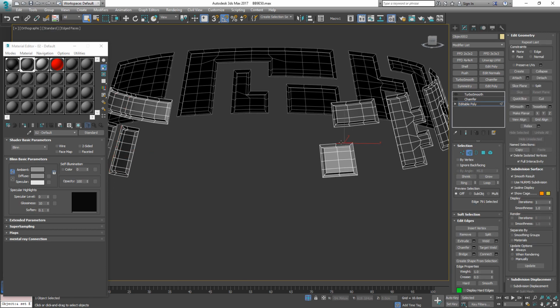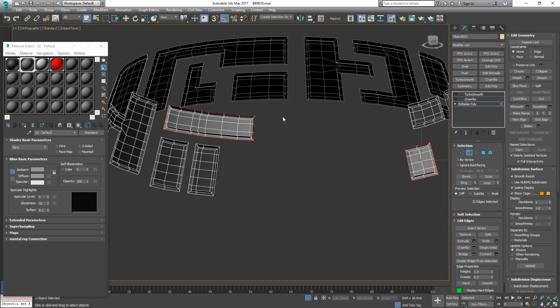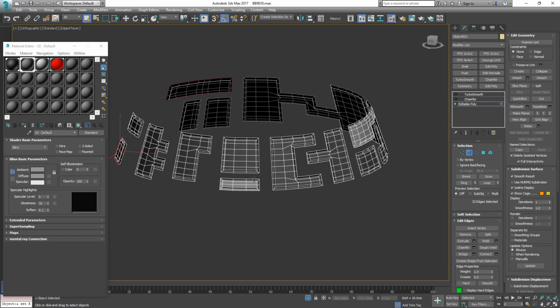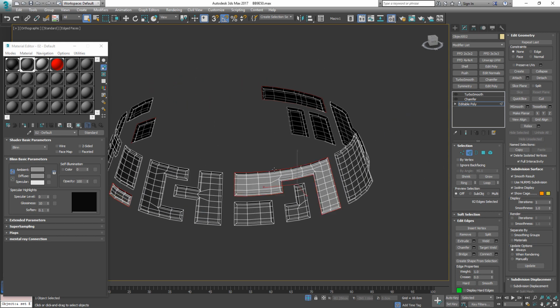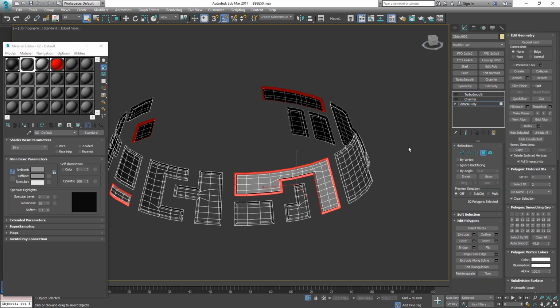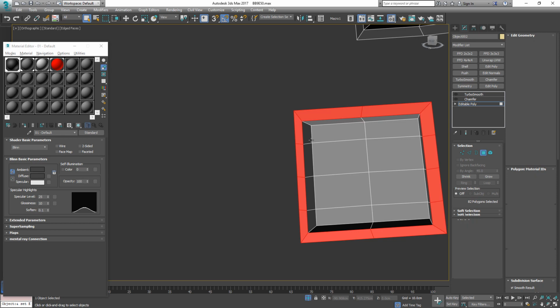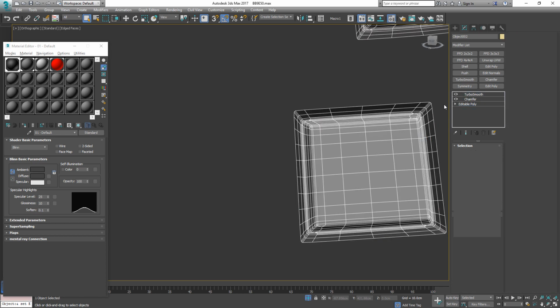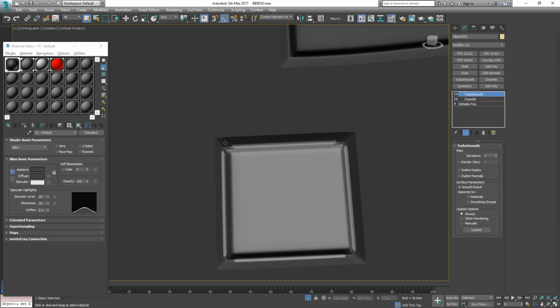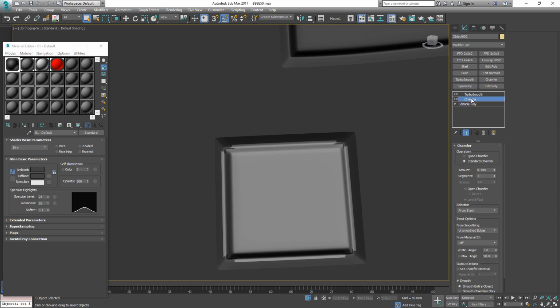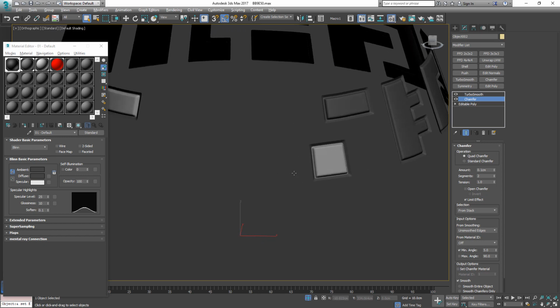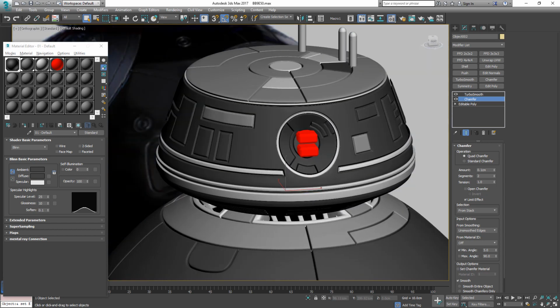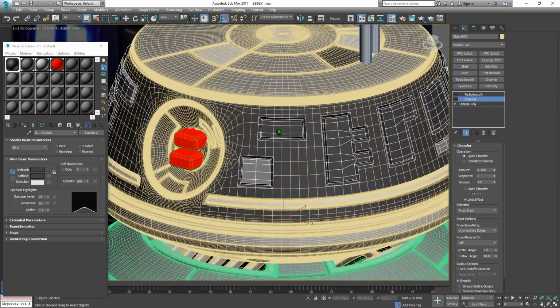And let's see what else we got. We need to select these edge loops here on the outside for each one that we just added the color to. Convert it to polygon. And now just add that black color here so that this edge crease there doesn't actually get that information. And that looks kind of how we don't want to have it. So let's change that to quad chamfer here on our chamfer modifier, which gets rid of it. And now we have our details here in place.